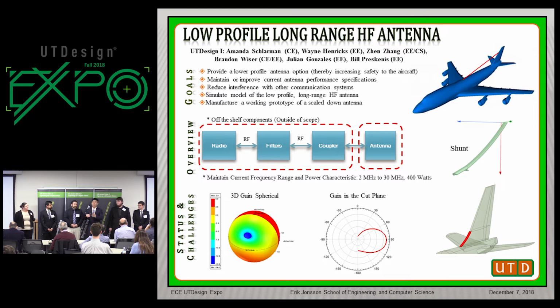So based on different aspects of materials of study, such as conductivity, resistance to oxidation, and the price, we are choosing aluminum as our main material for our prototype building, which is the most commonly used material for HF antenna design. And then we are planning to scale it down 4.9 times in order to make our construction realistic and make the frequency fall into our testing range, so that we can test our actual antenna. We're going to be focusing on 142 megahertz.